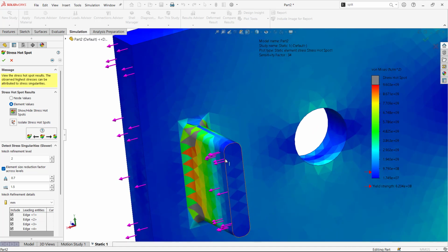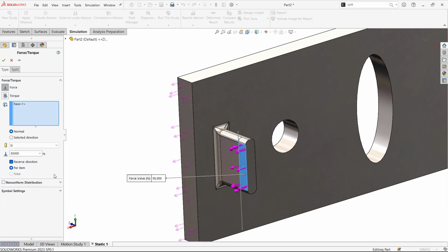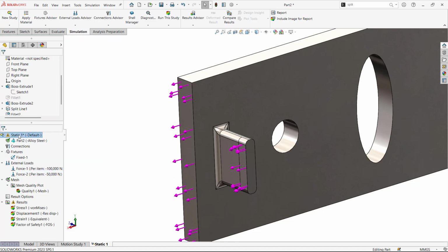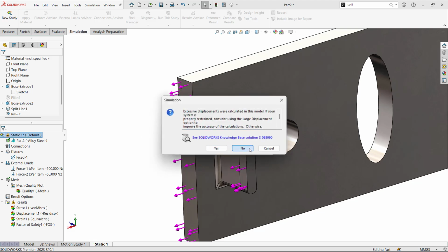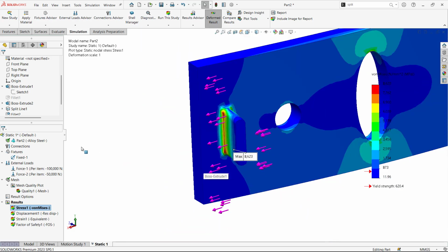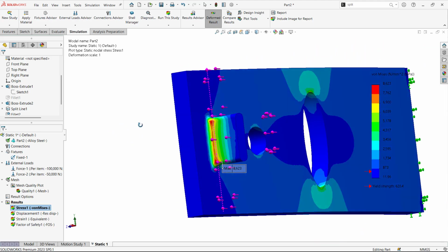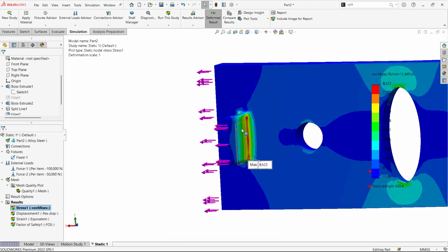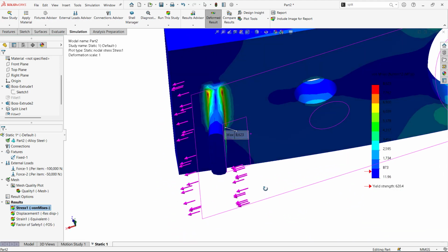Now in short, for this particular fringe, 85,000 Newton force is too much. Let's just reduce it to 50,000 and try to run this. I just want to avoid that stress hotspot, so I'm trying to make modifications in the model. Actually, design changes I should do. I should not reduce the value. Now I could see this particular frame is still not considering this particular load case.